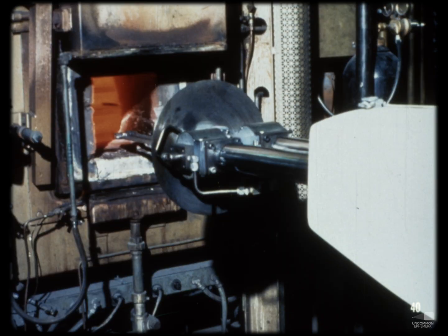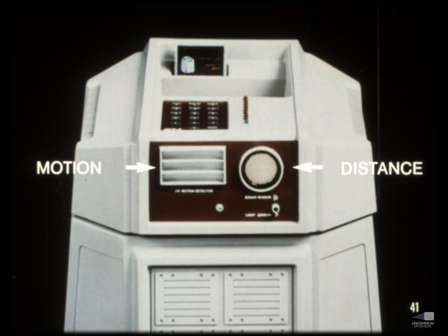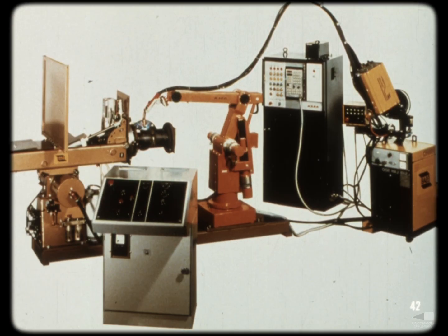Infrared detection systems are used to give the robot the ability to sense the presence of heat. This information feedback can give the robot the ability to select only those materials which are at the proper temperature for subsequent handling. Ultrasonic sound systems can be coupled to the robot control system to give the robot the capability to sense motion and measure distance. The signals that actually make the robot's various joints move are created by the robot's controller.